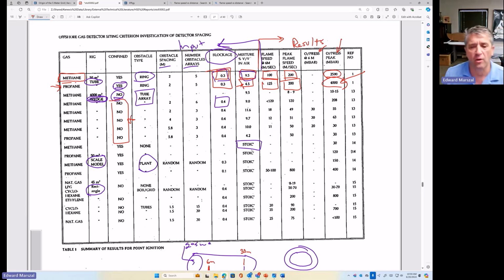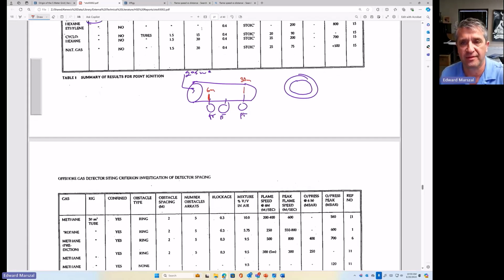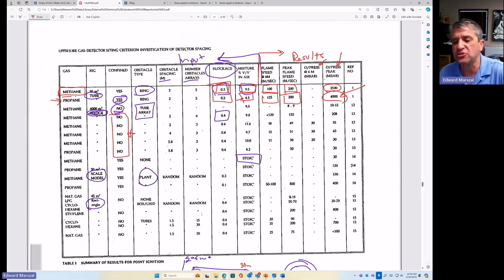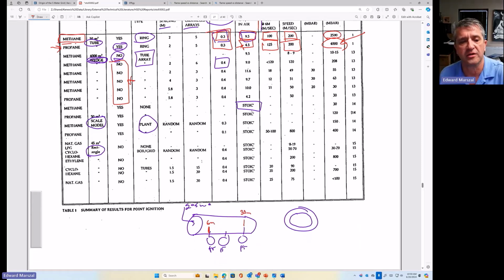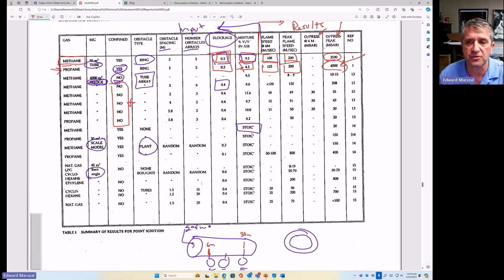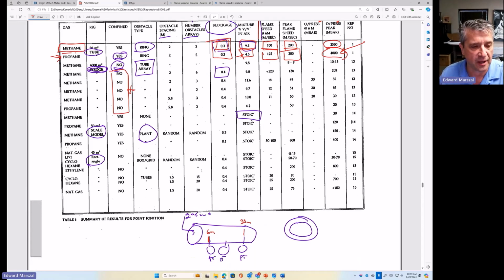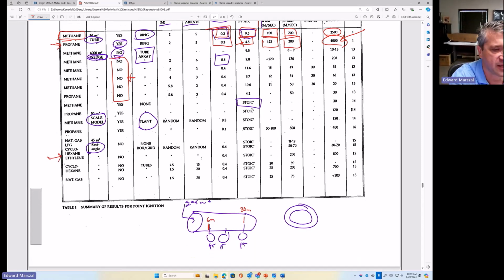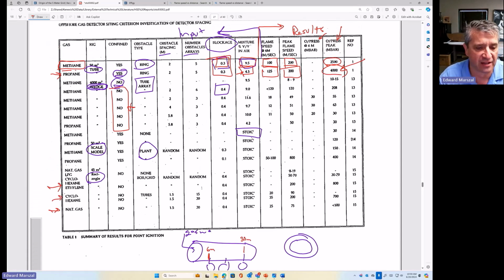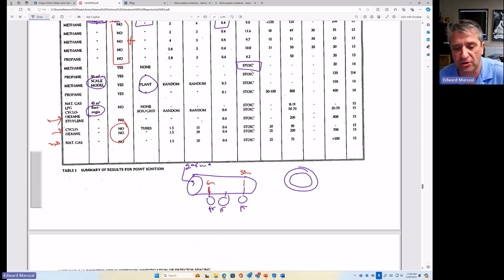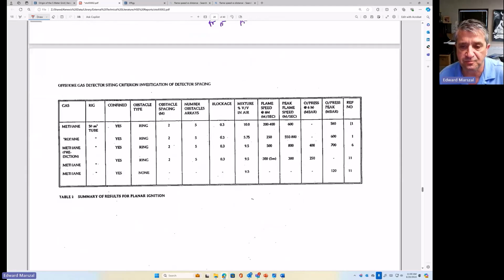Let me explain a little about why confinement is going to increase the flame speed. Look at this chart, and I highly recommend you download it to look at the different obstruction ratios, the different items like cyclohexane and natural gas, and what overpressures you're able to achieve at different degrees of confinement, different obstruction ratios, and different mixture concentrations.